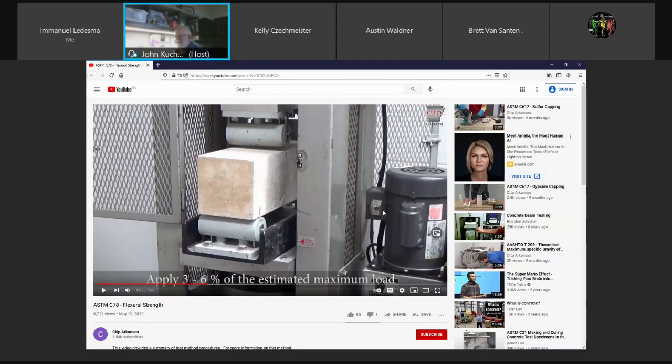You've got your rate of speed preset from previous ones on a beam. It may vary a little bit, so you make an adjustment as soon as you start loading. It doesn't take long to get that rate of speed. Plus that indicator, your digital indicator, gives you the rate of loading at all times. So you just turn your oil, it's based on oil pressure. Increase the oil, decrease the oil pressure, and that adjusts your speed of loading.